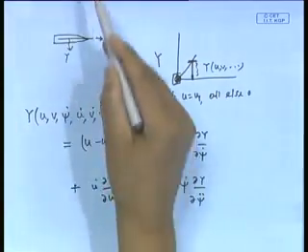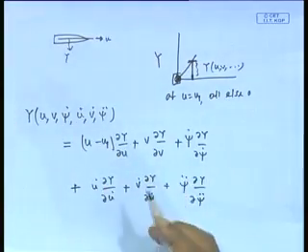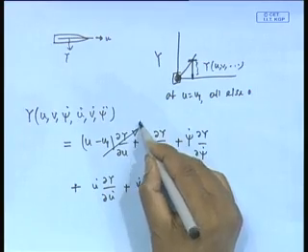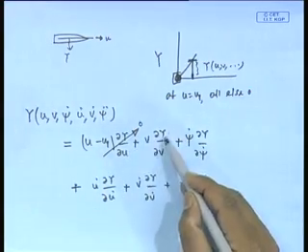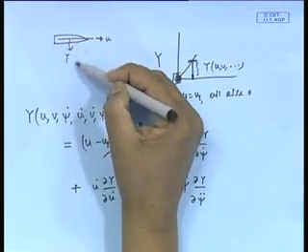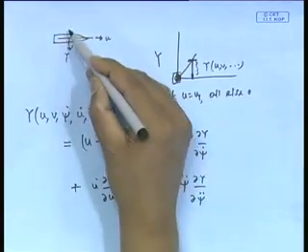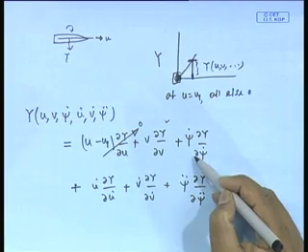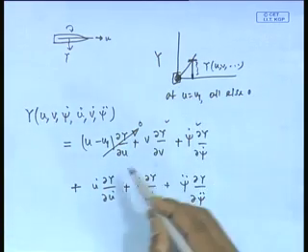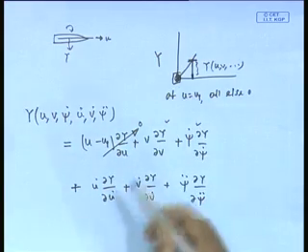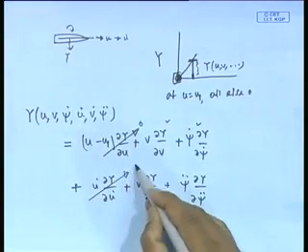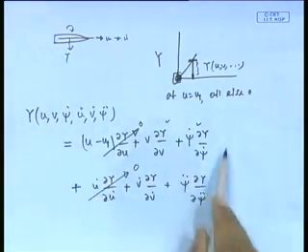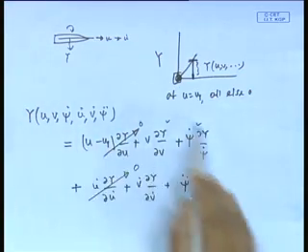What is the change? If I change this side, is there a change in the Y force? No. It is because of symmetry. So, this goes to 0. Similarly, but this does not go to 0 of course, because if I give a V here, there will be Y here. So, this is not 0. If I give a rotation here, this psi dot is rotation, also is not 0, because if I rotate there will be this force. But about this again, if I accelerate here, what is my Y force? 0. So, you see, I therefore end up getting an expression which has only these 4 terms.